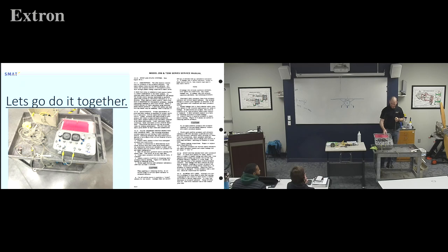Okay, so that's this device, and what I'm going to do is we're going to roll it out there. We're going to do this on the 414 because the 414 tests good, and then we'll have group one start with Anna on the Beechjet. So cross feed is just bypassing that. So then I would want to vent, well, let me think through that. I never want lower pressure on here, so we'll vent this one first. Bring that back down. The cross feed's still open, so it's bringing them both down.